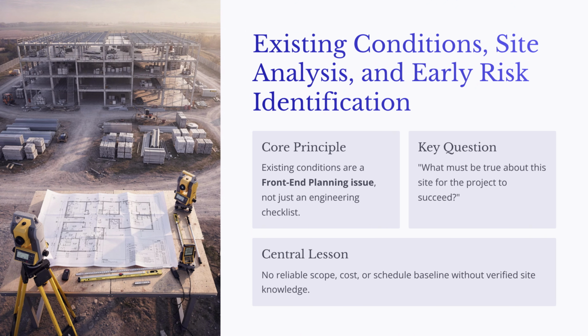If the team does not verify site knowledge early, the scope, cost estimate, and schedule baseline may be built on assumptions rather than facts. Unknown utilities, weak soils, limited access, permitting constraints, hazardous materials, or insufficient utility capacity can all change the project after major decisions have already been made. The central lesson is simple: there is no reliable scope, cost, or schedule baseline without verified site knowledge.